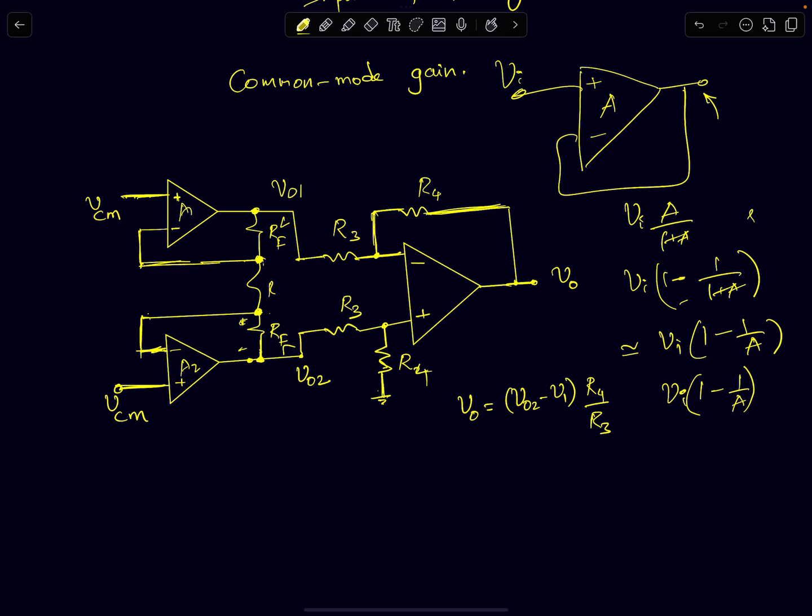Just keep this programmability point in mind. We will later talk about bandwidth of amplifiers, and this is very helpful there. So now I'll come back to this discussion. We said CMRR is mainly determined by the second stage.